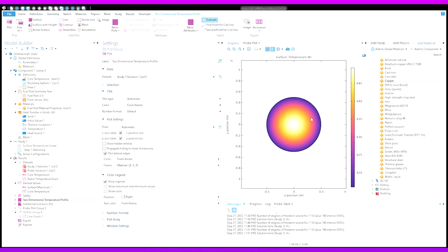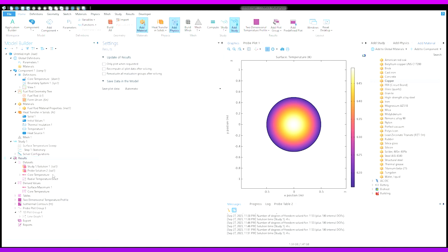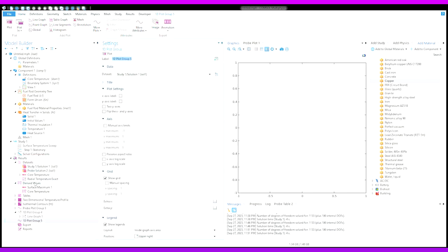So in order to access this, and I'm on step 2 of the plotting and export section, we have to right click and select 1D plot group. This can be used to look at a lower dimension. We could have done a 2D plot group if we were in 3D, so just keep that in mind to try and think generally. When we click that, up in the top ribbon it'll give us some common plots. I think a line graph will do just fine for this, so I'll click on it.